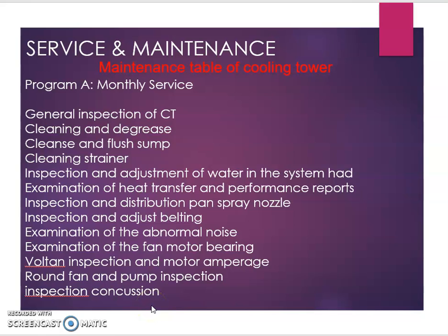Some buildings also have their own facility personnel and facility maintenance. So they can also do a monthly service and monthly checking for the cooling tower. For example, they can do a general inspection of the cooling tower to see whether it is in very good condition or not, whether there is any broken body of the cooling tower, cleaning and degreasing the cooling tower, cleaning and flushing, and cleaning the strainer to avoid clogging of water.